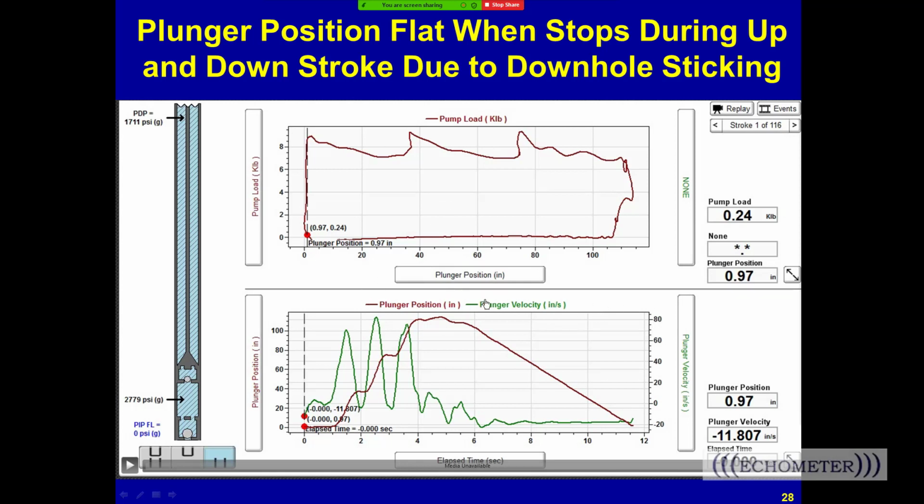Well, you have to take away the mechanical friction. There are different kinds of rod guides. Most rod guides have some reinforcing in them that makes them abrasive. Some rod guide material is slicker. There's a new material that's more expensive called polyether ether ketone that seems to be slick.